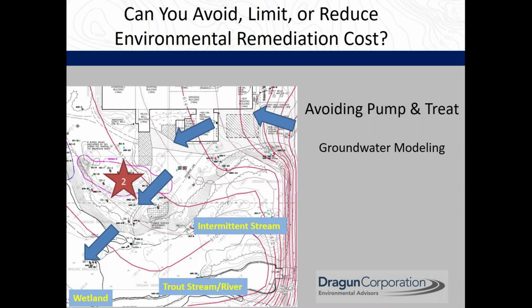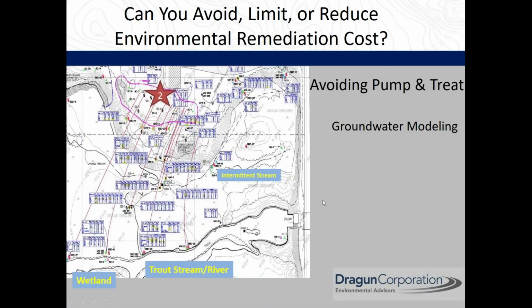And we were able to provide even more definition to this groundwater, beyond just the contouring, by using groundwater modeling. And we used a MODFLOW model to better predict where the contamination from specific wells was going. And these red lines that you see on this slide show particle tracking from known contaminated wells. And these lines show where the most contaminated groundwater was discharging.